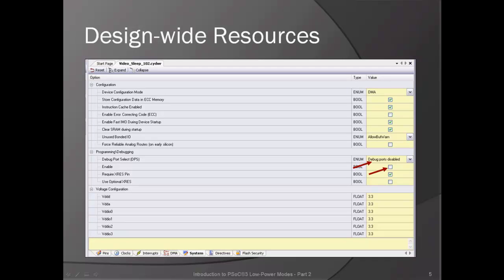One thing that is often overlooked when developing a low-power system using PSOC Creator is the built-in debugging capabilities of PSOC. Because real-time debug is available in the PSOC3 device, the debug interface can remain active even when the device is in a sleep state. This may result in higher power consumption than would be present in the final application. To eliminate this possibility, when debug is not needed, you can disable the debug logic. It doesn't consume a lot of power, but sometimes can be a distraction. Just be sure to enable it again if you need to run the debugger.